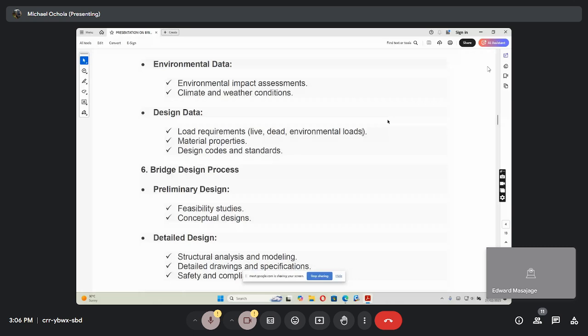So properties like reinforcement. Today, even in building, I think we are now into T type, which is 500 MPa, and so forth. It used to be 460. But if you go and do testing, you may find even more than that, but that is specified. So the design data you can get from design codes; standards are there. We shall give some literature later.